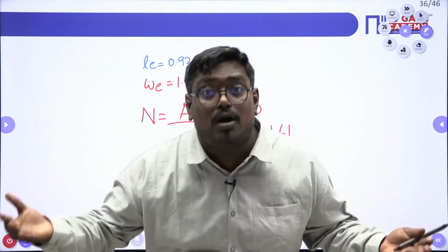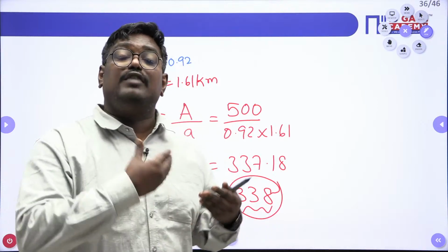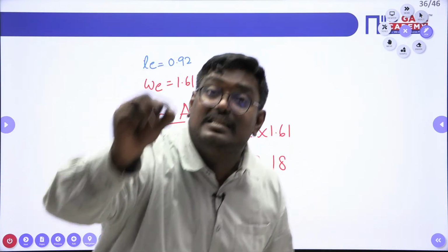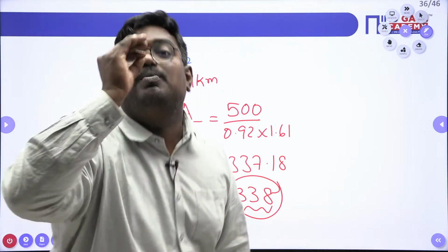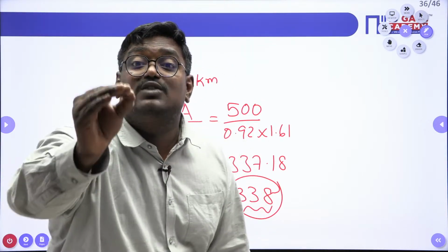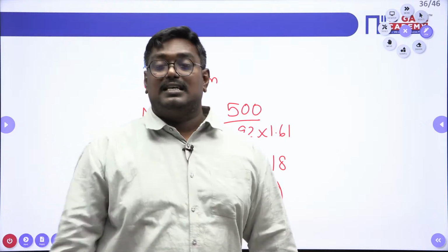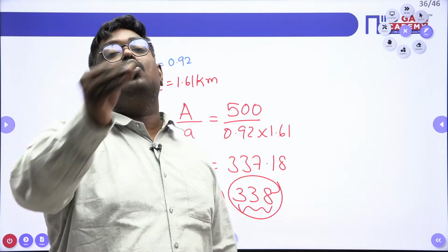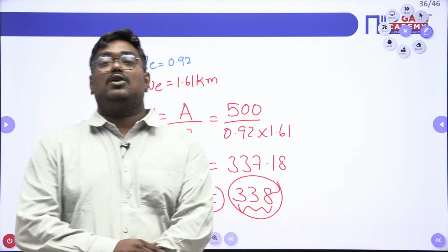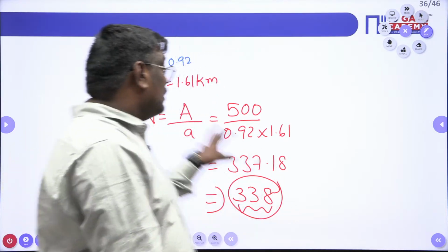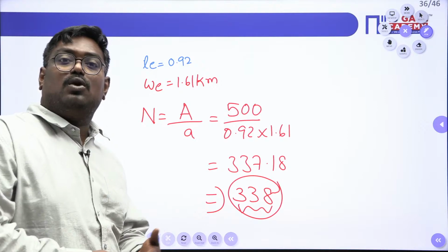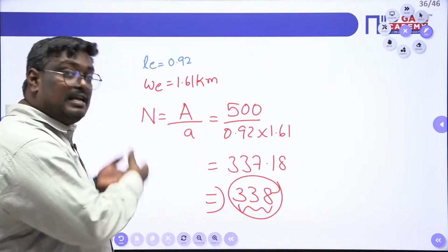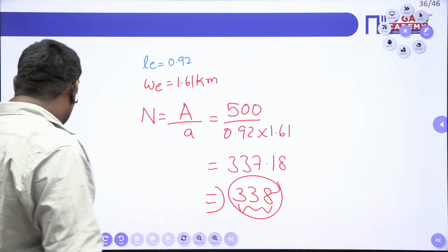Why is it not part to whole? Because if it is whole to part, the errors will not accumulate. Or you can say, when working from whole to part, the errors will not increase. And the second principle of surveying is locating a point with respect to two known points. So more the control points, more the accuracy. Similarly, more the number of photos, more the accuracy.